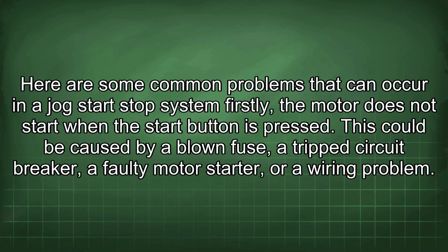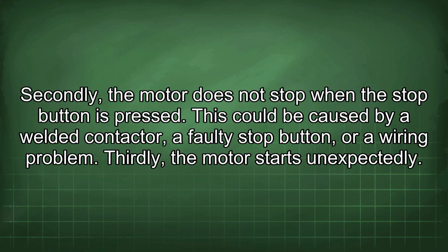Firstly, the motor does not start when the start button is pressed. This could be caused by a blown fuse, a tripped circuit breaker, a faulty motor starter, or a wiring problem. Secondly, the motor does not stop when the stop button is pressed. This could be caused by a welded contactor, a faulty stop button, or a wiring problem.